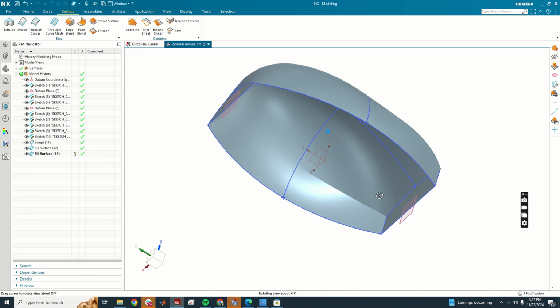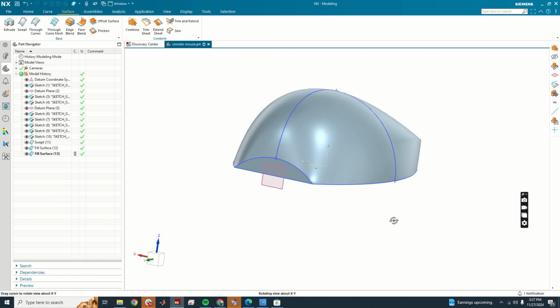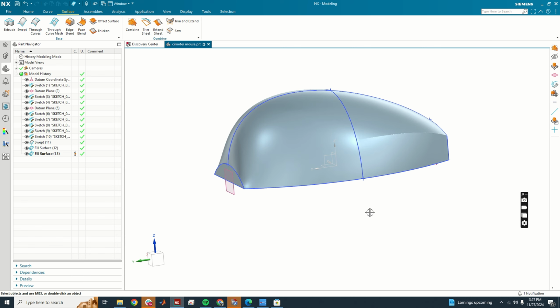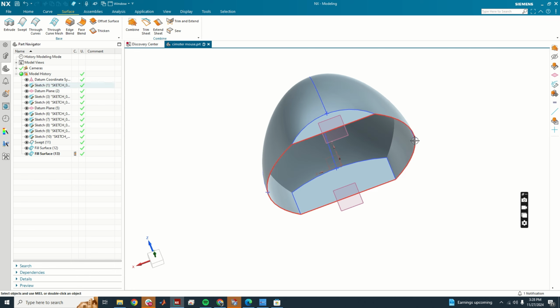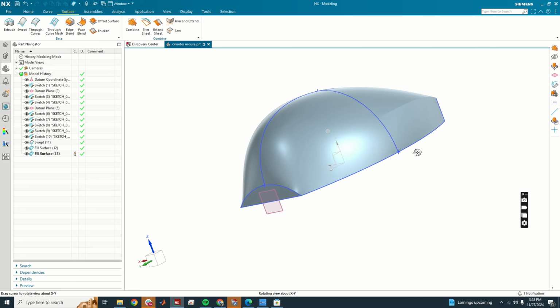The next thing that I'm going to do is create geometry. This is when I go from the surface modeling to the physical body modeling. So if I was going to say 3D print this house, or this mouse, I would want a housing that was, I don't know, 3 or 4 millimeters thick that I would print all the way around, and then it would house the electronics inside it.